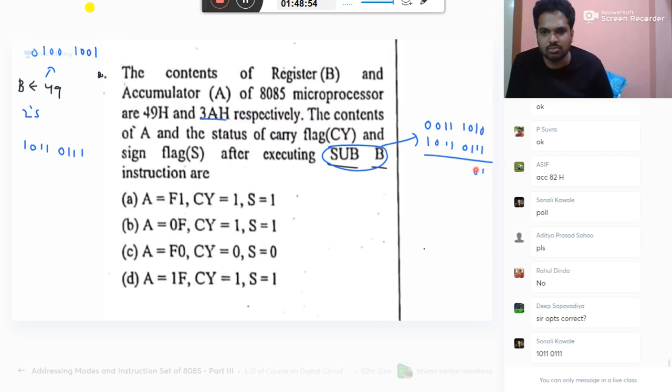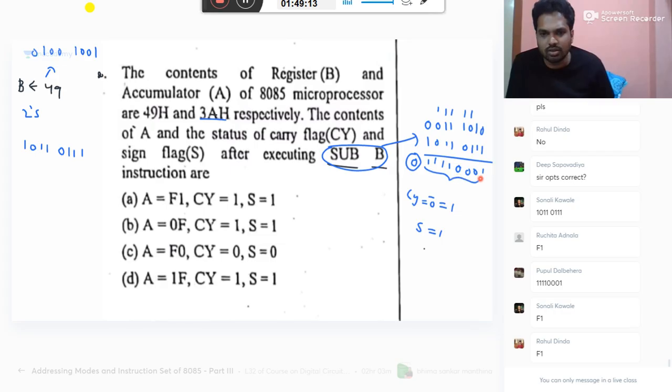Good. So let's see. This cannot be done now. Jump instructions, tomorrow we discuss. Okay. So I have uploaded this. So yeah, read this question. We can try this question. The following 5 instructions were executed on an 8085 processor: MVI A, 33; MVI B, 78; ADD B; CMA; ANI 32. The accumulator value immediately after the execution of the 5th instruction is.